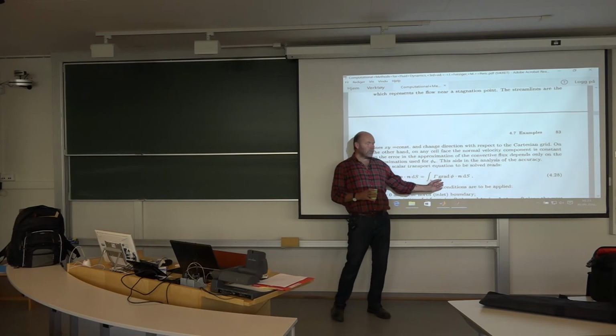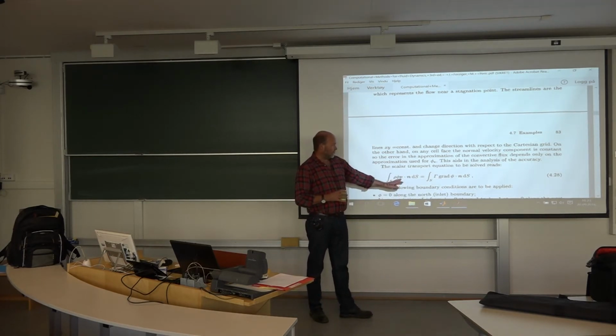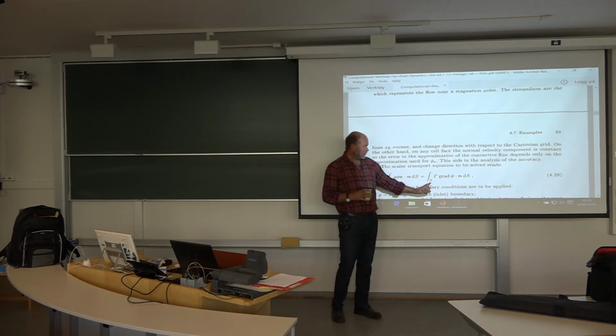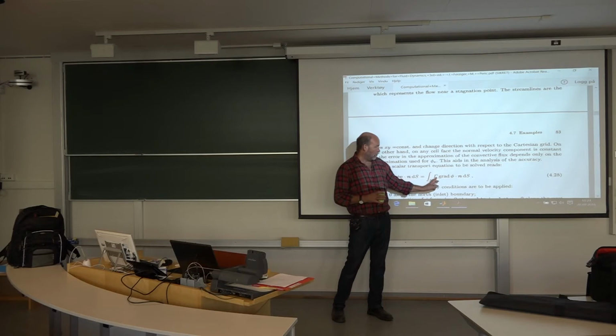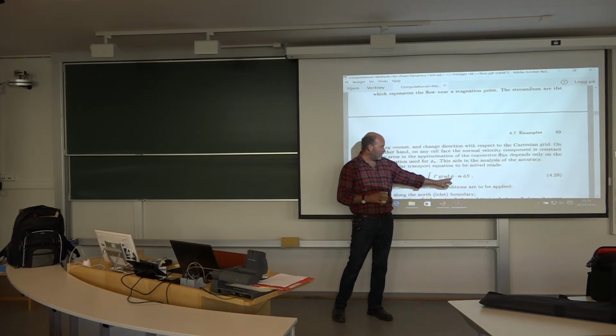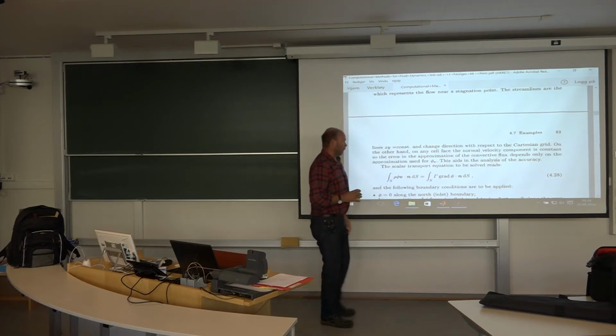advection diffusion equation. If you look at it, the velocity field is given. That one is known. So here we have a sort of an integral of the unknown phi around a surface. Also here, a surface integral of this gamma, the diffusion coefficient, and then the gradient of our unknown in the normal direction of the surface S.